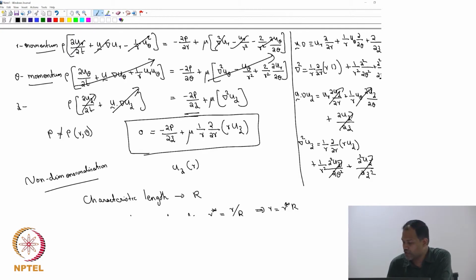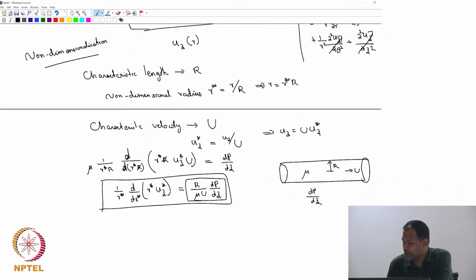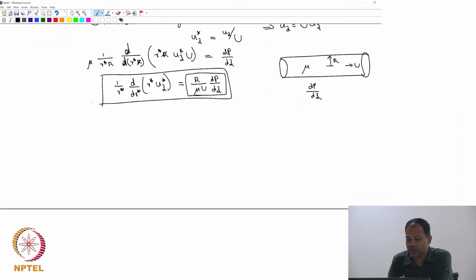But now we have gotten rid of all that, and the entire equation has become non-dimensional. We have also figured out that if we want to change the flow in some fashion, this is the quantity that we should look at, nothing else. We do not have to really care about anything else. In fact, this is going to be related to the Reynolds number. We will see that at a later point, maybe when we substitute for U, which we will do later.